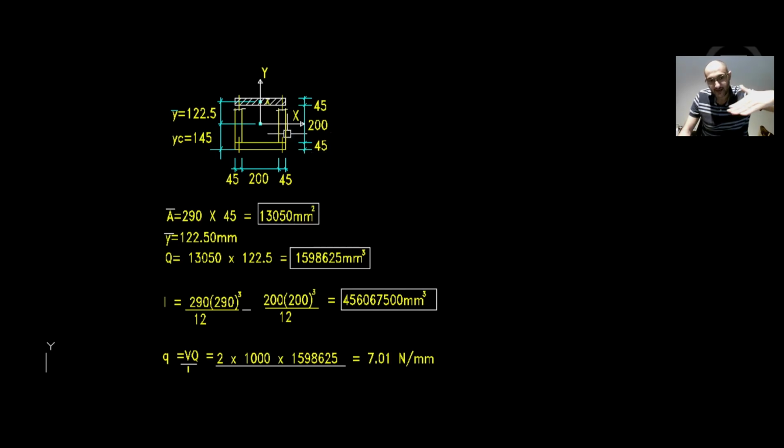So we can't shear halfway. Shear means you cut through the entire cross section throughout the entire beam. All right. So if we go through the top, we will shear right through, and that shear above the x-axis, which is the horizontal axis, the major bending around the x-axis, that shear will be symmetrical to the shear below the x-axis. So if we shear at the bottom, it will be the same thing. So we can shear it at the top or the bottom, and we can take Q, this hatched area, from that top, or we can do the same thing from the bottom, one or the other, and that will be around the major axis.